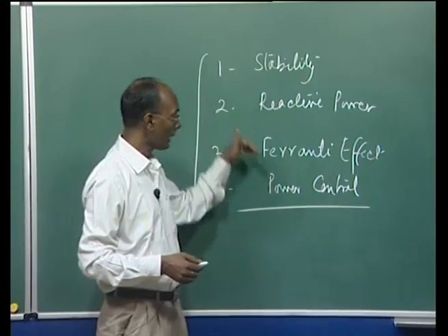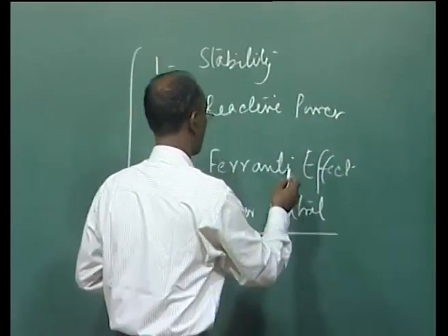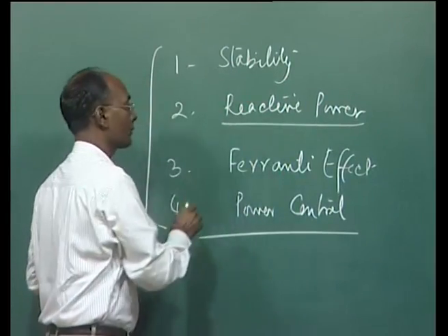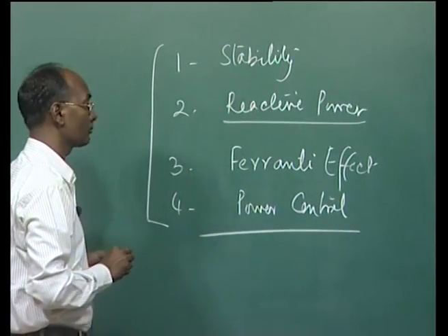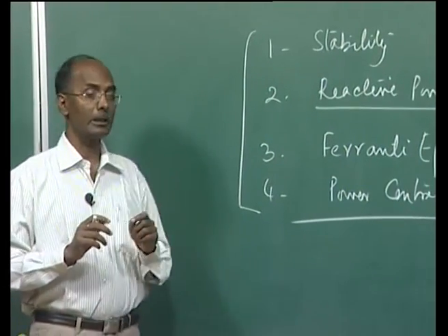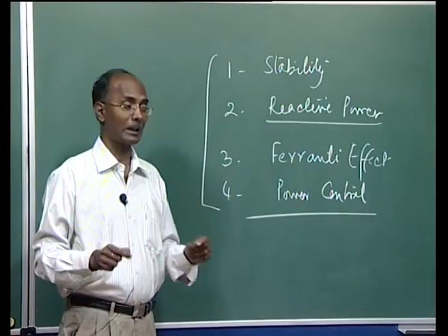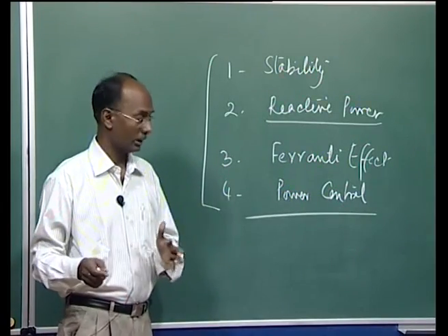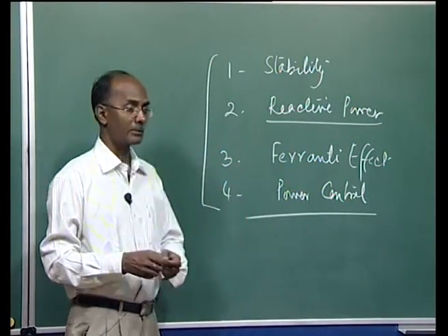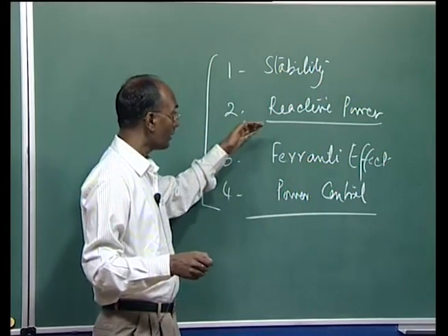To avoid these, DC transmissions came, because of the reactive power. You can see the first HVDC transmission system, which came between Sweden and the Gotland Island, was basically due to the charging, because a 70 kilometer cable at that time was not feasible. Then it was realized that we can go for DC cables, and these were feasible.